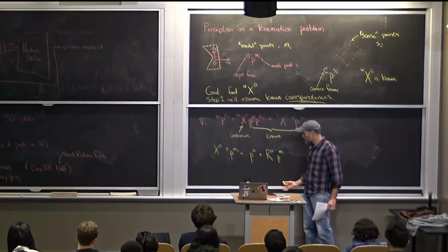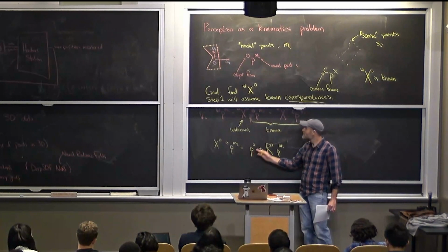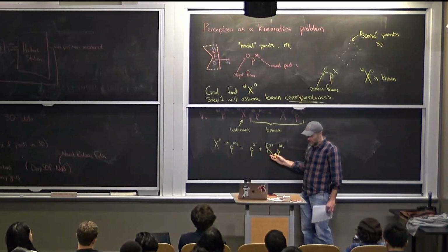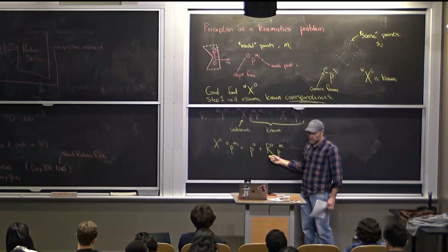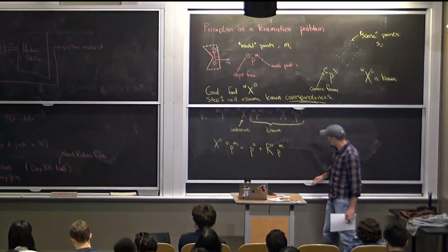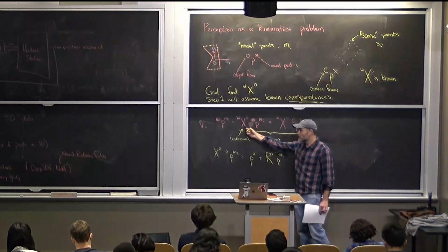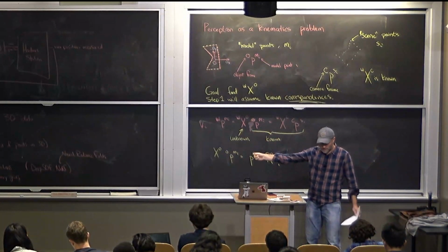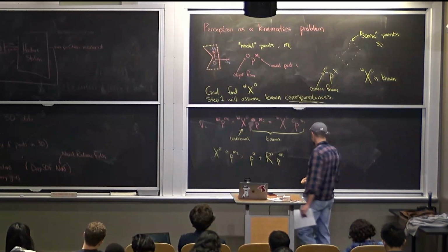The rotation, you'll remember we have lots of choices about how to represent it. This is always 3 numbers, basically, in 3D. In 2D, it'd be 2 numbers. Here we have many different ways we could possibly represent the 3D rotations, but somehow we need to search over these. And that's the question. So solving this is actually an inverse kinematics problem. Given the data, the points in space, we're trying to back out the orientations and rotations. So this is an inverse kinematics problem.